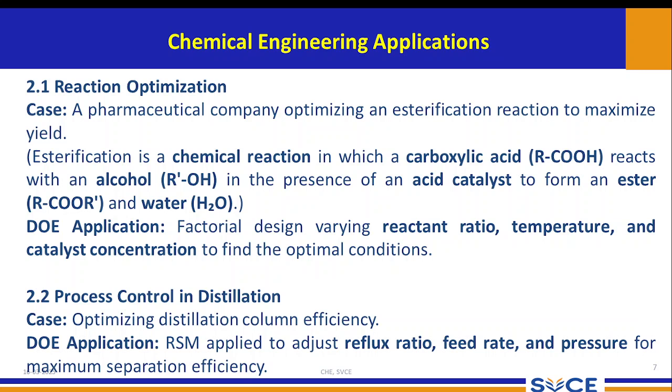Coming to process control in distillation, optimizing the distillation column efficiency. How to make sure that a column is efficient? We need to adjust the reflux ratio, feed rate and the pressure inside the distillation column for maximizing the separation efficiency.